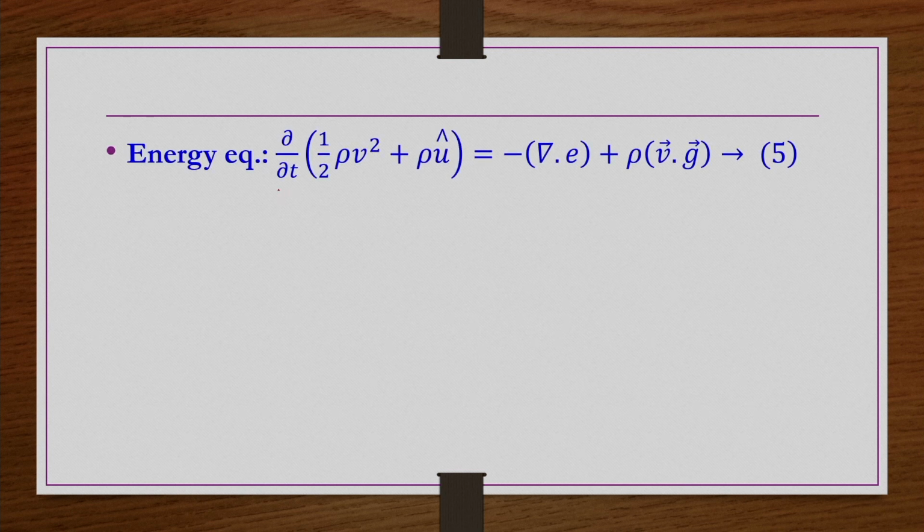Right. Now, the energy equation, equation number 5 in the generalized form, this is what we had. So, this now we have to simplify as per the constraints of the problem. So, steady state, so this term is 0 altogether, and then we are not taking gravity. So, all the terms that have gravity we can cancel out altogether. Even after expansion, each and every term associated with this one has the gravity g term. So, we can cancel out altogether.